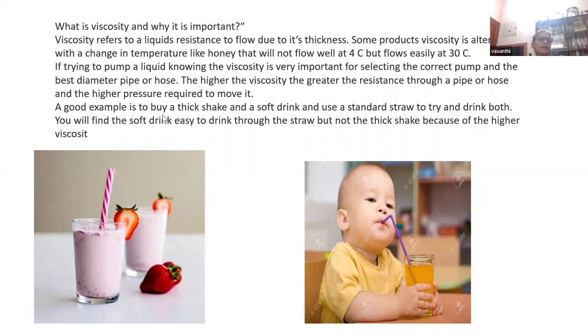And even in order to pump oil or liquid, you have to design knowing the viscosity. The viscosity of the liquid to be pumped is very important in order to decide what type of pump is required, say if you are pumping raw petroleum from a petroleum well, you need to pump the oil out.